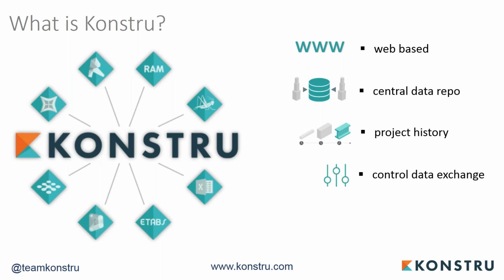And the other thing that we've added, and this goes a bit to the point of it's not useful having to regenerate an entire model every single time, is that yes, we can do updates to existing models. We're also going to show that today, but we also let you specify how you want to update your existing model. So if you are not interested in overwriting your material assignments in the existing ETABS model with new materials coming out of Revit, then with Konstru, you can simply say, okay, yes, give me geometric updates, but do not give me material updates for these elements. So we have ways of doing that.